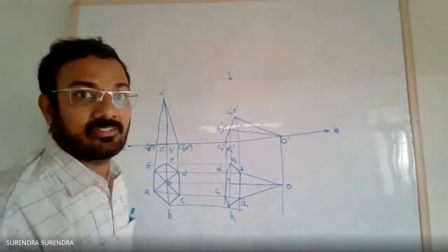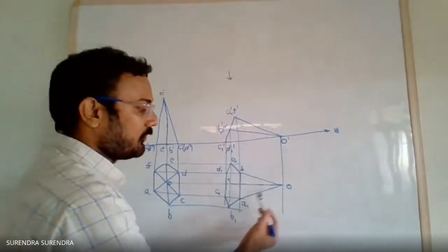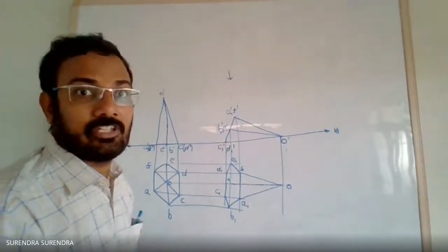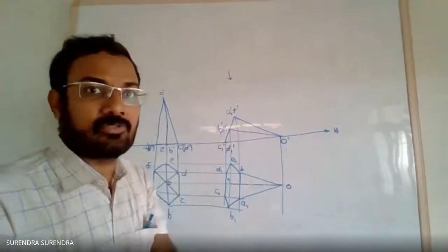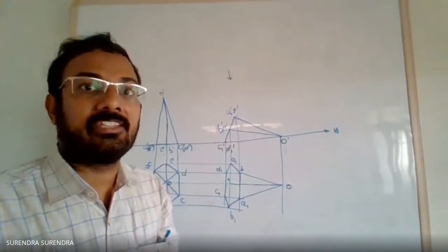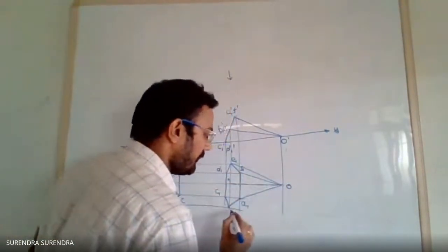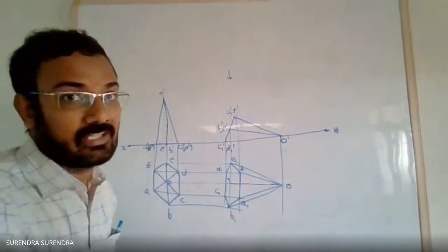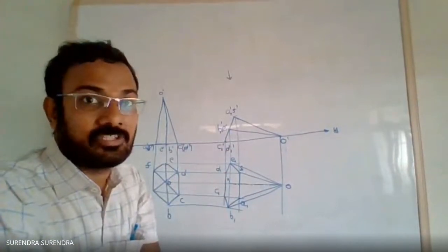But is it visible? If you observe in top view, EO and BO are on the outermost boundary. Whenever in any solid object, the outermost boundary must not be a hidden line. Whatever position it comes in, we should take it as a general rule that the outermost boundary is always visible. So join EO, BO with continuous lines.